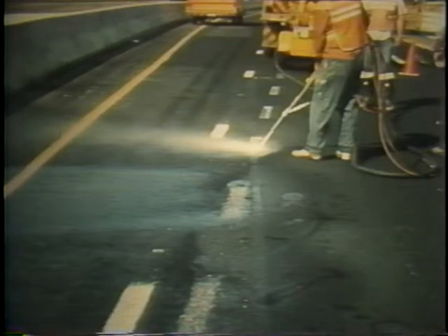A shadow line is always left. The line is not too noticeable in daylight, but at night, under headlights, the remaining dark line could easily be confused with a painted stripe. One of the most successful methods is burning using oxygen. The partially melted asphalt is brushed over the aggregate before it cools, and the shadow line is not a problem.